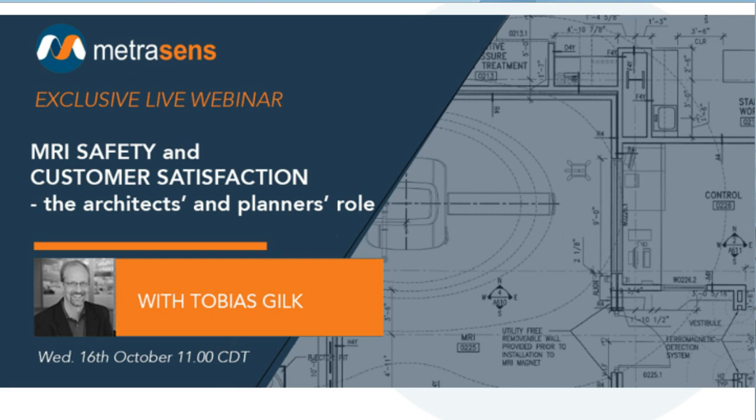When the detectors are a part of the door, or immediately at the door, in the user's mind, if they're walking up to the door and they open the door and the alarm goes off, they're not clear whether the alarm is for them as an individual or if the alarm is related to the door opening. If we can physically separate those two elements, approaching the door and opening the door, then there's a better likelihood that the alarm condition informs the person that the alarm is about them and not so much about the door